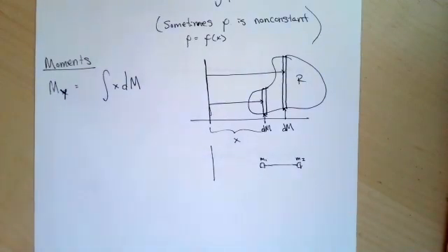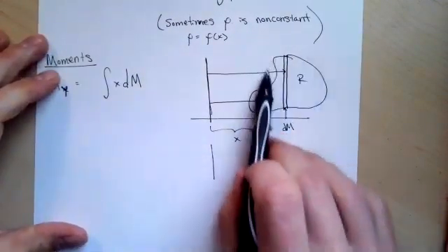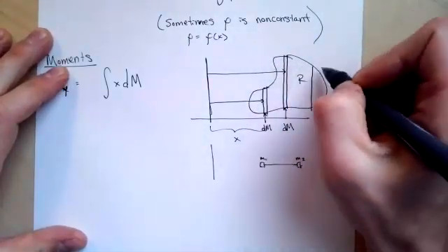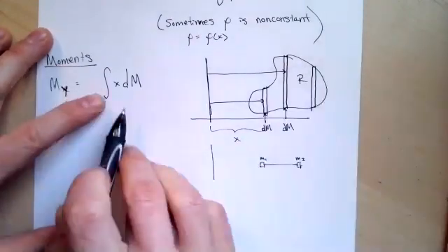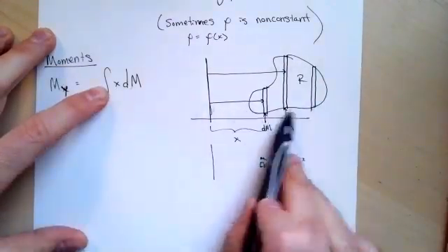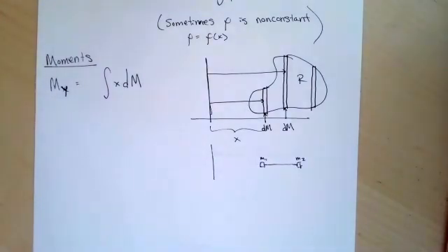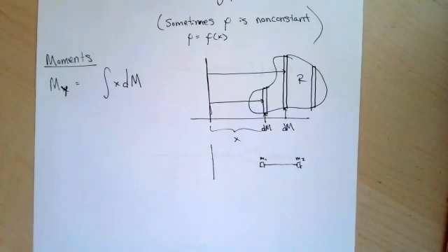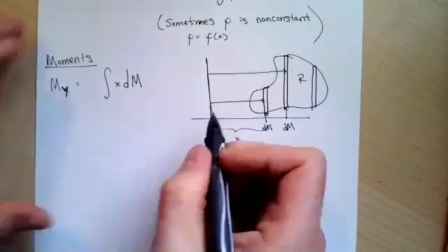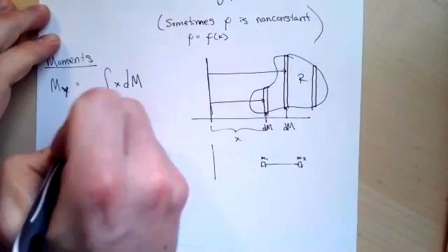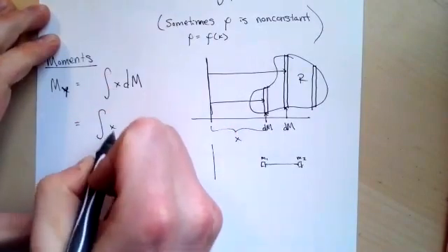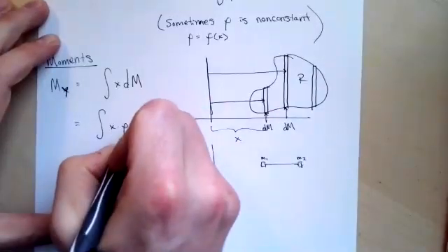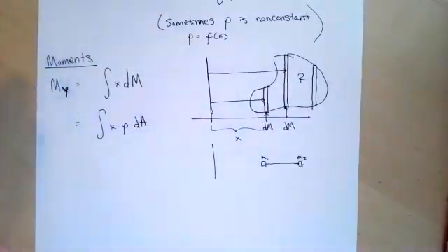And so, of course, what do we want to do in a Calc 2 sense when we have a continuous shape? Well, we're cutting it up into all these infinitesimal slices, computing each individual slice's contribution to the moment of inertia and adding them all up with our integral. So dm, of course, is going to be x times the density times the area of each slice.